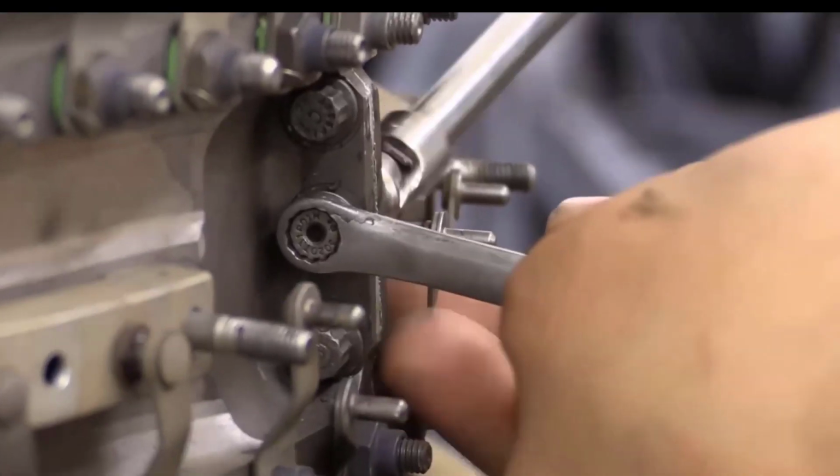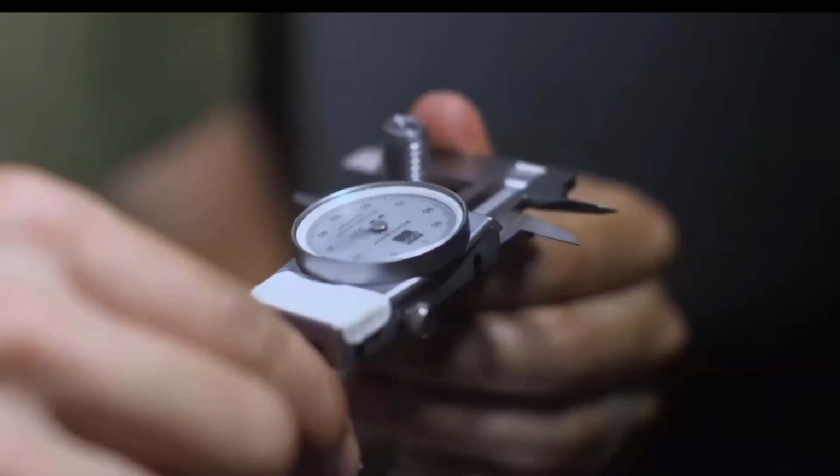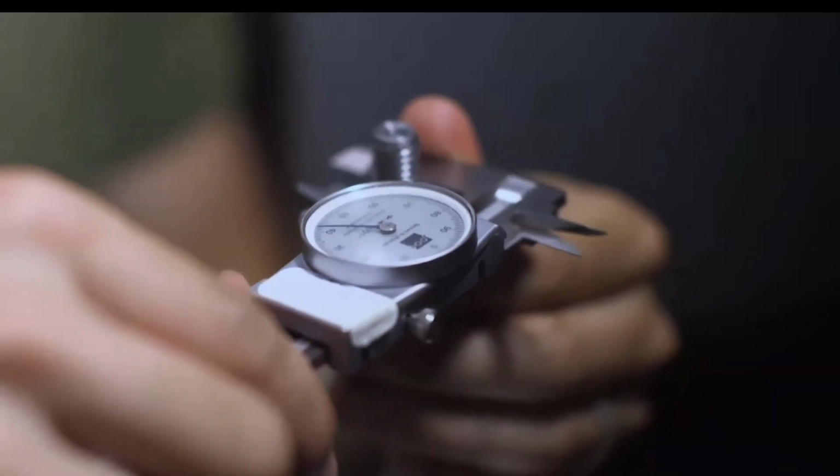You should do your absolute best to avoid subjecting screw threads to significant shear loads. The decreased area at the root of the thread makes this the weak part of the fastener, and the threads bearing on the mating pieces will lead to fretting. Instead, it's best to transmit shear loads with dowel pins or shear bosses.